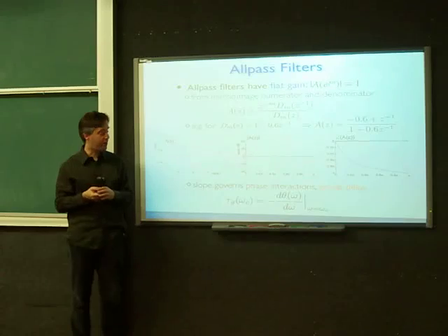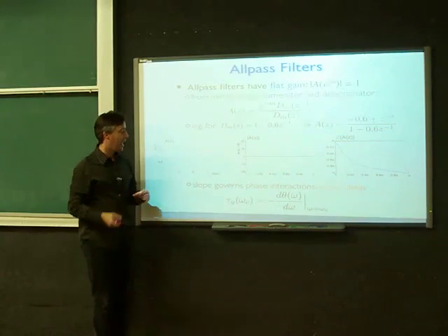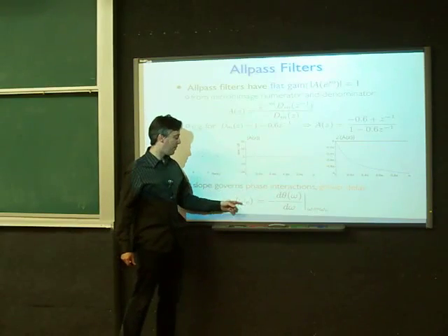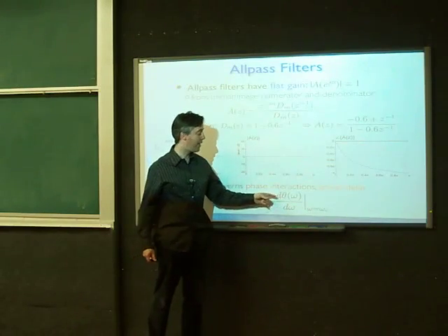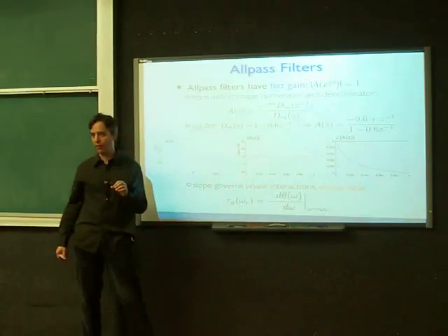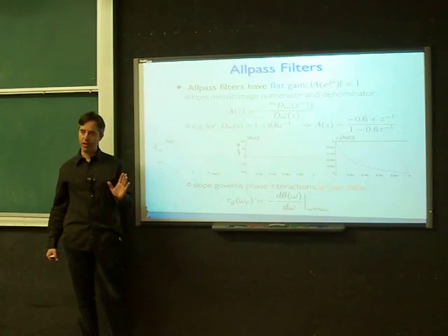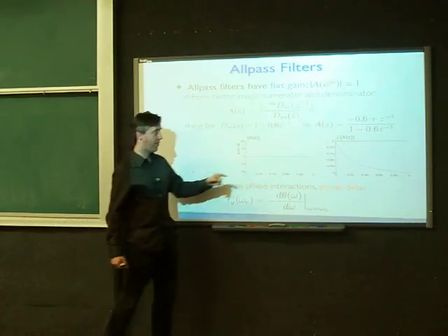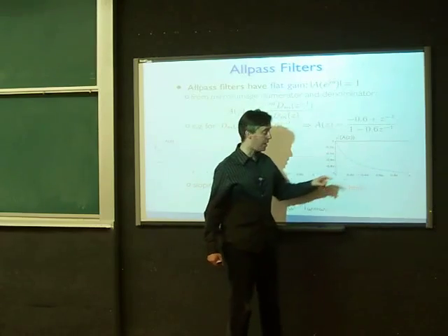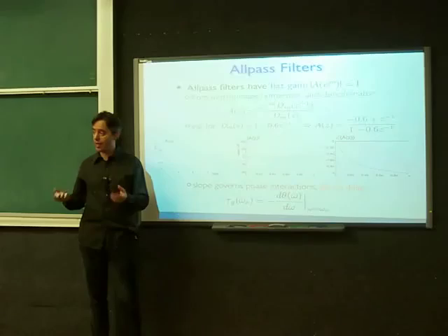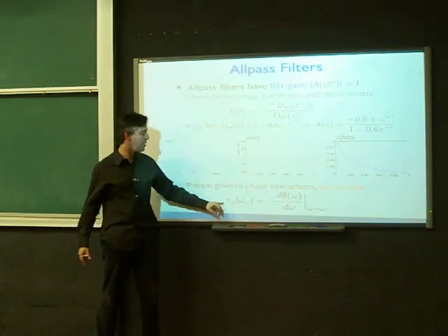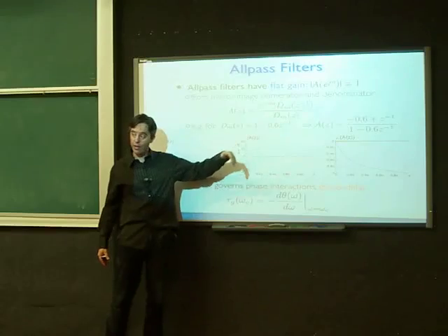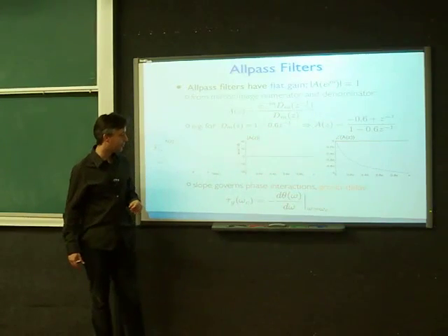You affect the envelope of those frequencies, and it's called group delay. And the definition of group delay depends on the slope of the phase function, not the absolute value, but the slope. And there's this difference between group delay and phase delay. If you put in a sinusoid and look at its fine structure, look at how much the actual zero crossings get delayed, that's just the phase response here, the actual value of this curve. But if you modulate that sinusoid, you put some kind of envelope onto it, put it through a system like this and see how much the envelope gets shifted, that actually goes by the group delay, the local slope of the phase function, not the phase delay.